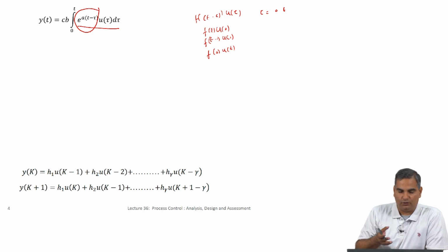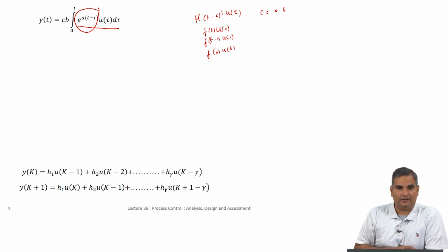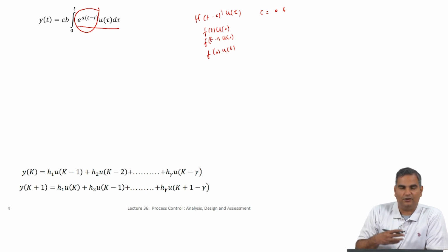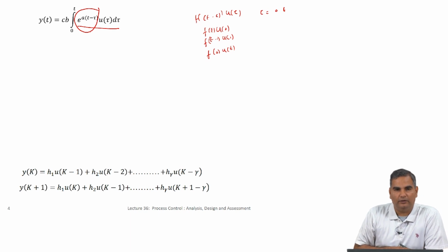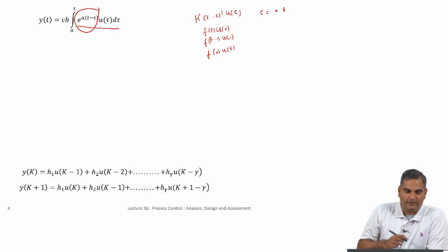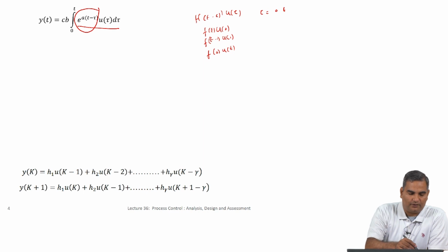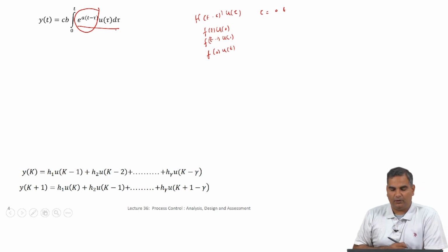One can actually show how this comes about with concepts such as zero order hold, and by actually doing this integration and showing that this is the form that you will get, but that is a little too much for this course. I am simply going to say how this happens and give you an intuitive feel for how these discrete models are derived. Where we are going is, from this continuous model we want to go to the discrete form.